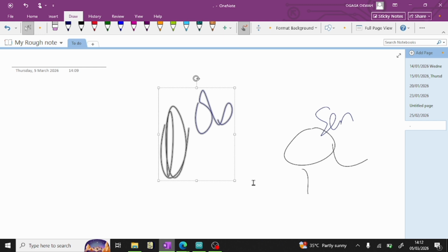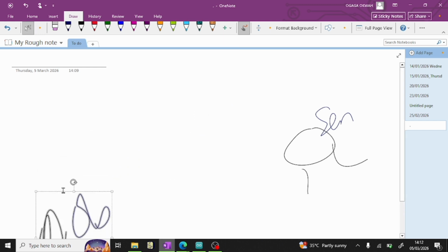Okay. Then for the delay time, when the sensor detects the object and sends a signal, so now the sensor is giving out a signal, high, meaning there's an object there. How long will that signal last? Even when we take out the object, how long will that signal last? Will it stay on? That period is known as the delay time. So how do we control the delay time?